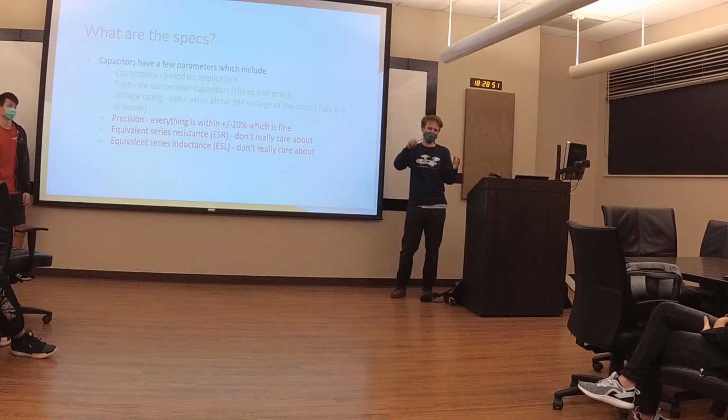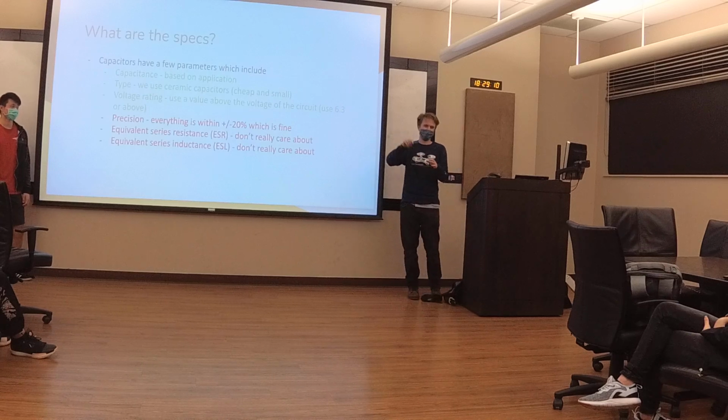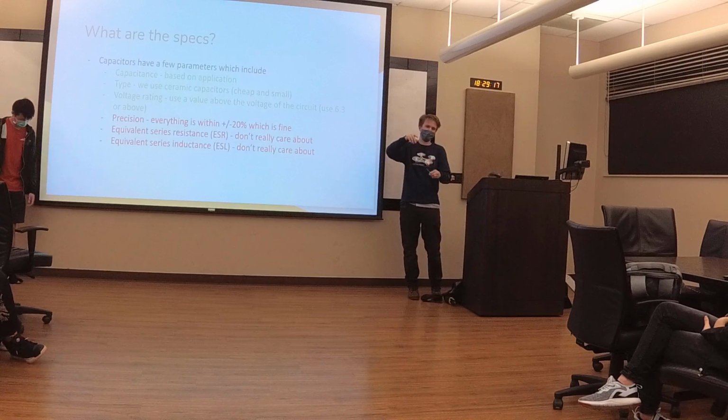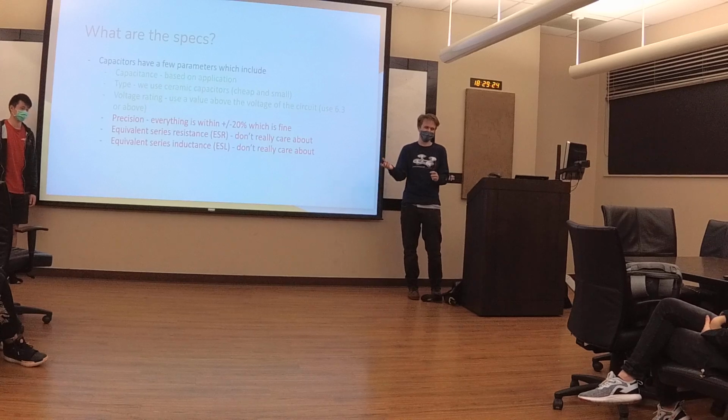The problem is if you're switching at 2.5 megahertz, you're guaranteed to have some noise pretty much at 2.5 megahertz on the output. The other thing is your microcontroller. It works at 100 megahertz, let's say for an example. That means the stuff inside of the microcontroller is switching at 100 megahertz. If something is switching on, it causes a small dip in current because it requires current to operate. If something is switching off, all of a sudden you have a bit of excess current. Pretty much any time the state of a circuit changes, something turns on or off, you're going to get noise.